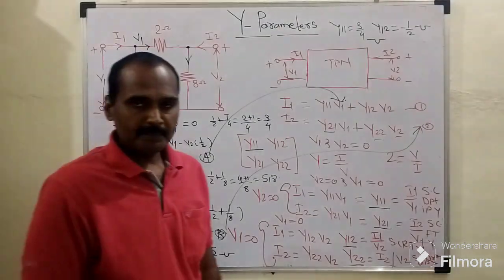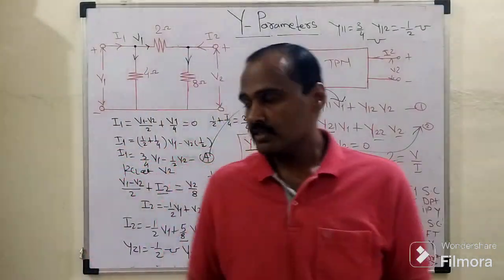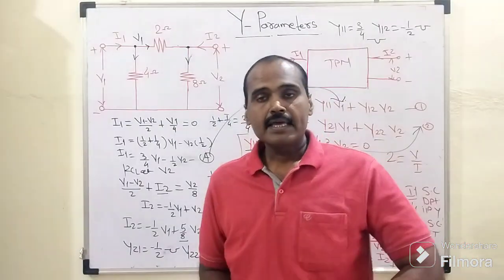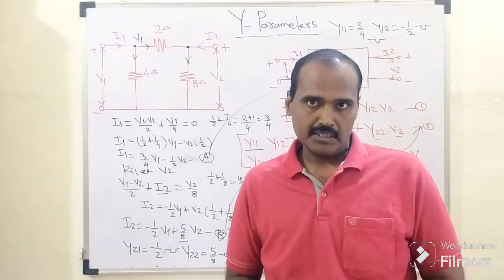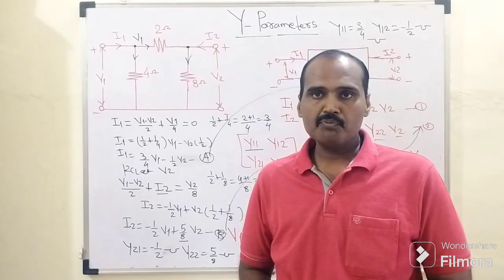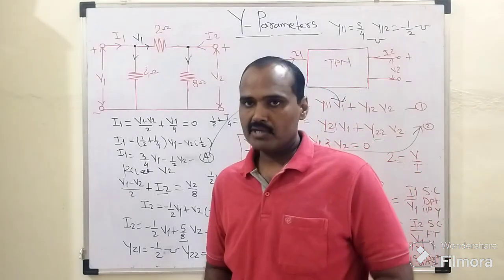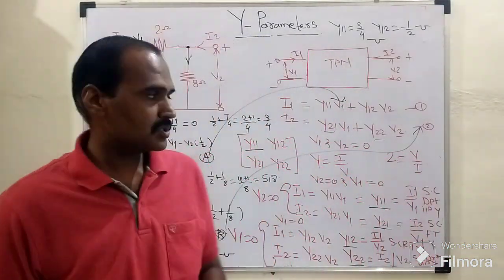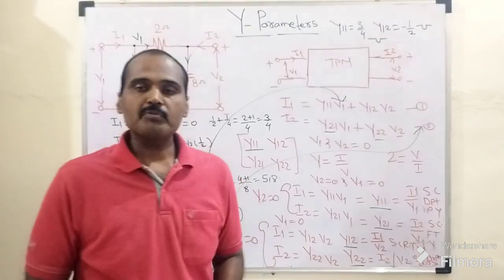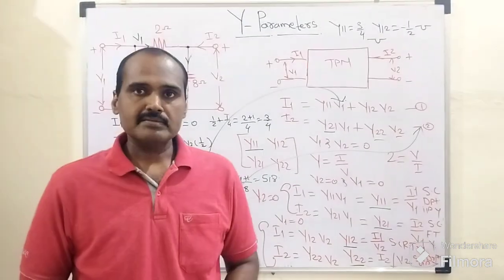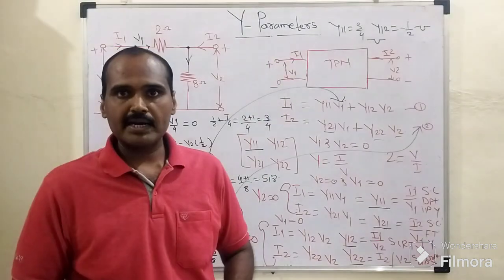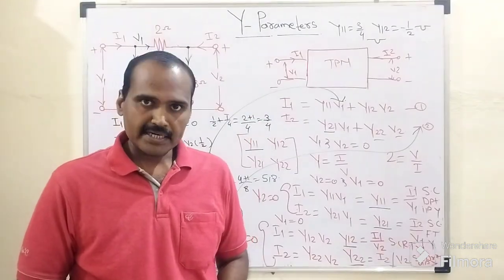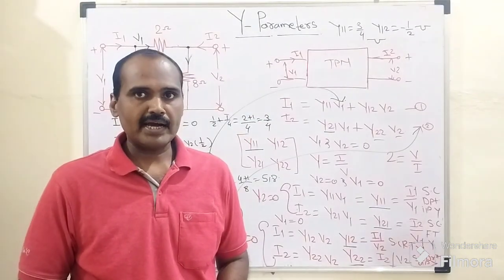So in this way, these admittance parameters have to be tabulated for the given network by using the Kirchhoff current law strategy. If we have a T type of network, then we are supposed to use the Kirchhoff voltage law strategy. I just hope we understand all these things belonging to the admittance parameters, another name for which is the short circuited parameters or the Y parameters.